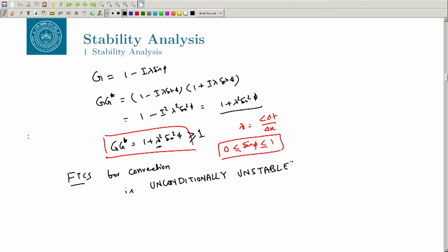Okay. So, that is why if you recall, when we tried solving this using the FTCS scheme for let us say advection of a square wave, okay, we saw that it started developing wiggles and then quickly it basically blew up. As you run in time, it will quickly blow up. It is supposed to be convecting with the convection speed. So, in this case its speed is equal to c. So, it is supposed to go like this, okay, but instead you will start developing wiggles like this and finally it will basically blow up, right. So, because this scheme is unconditionally unstable, right.